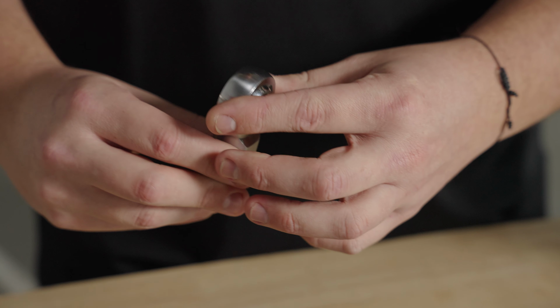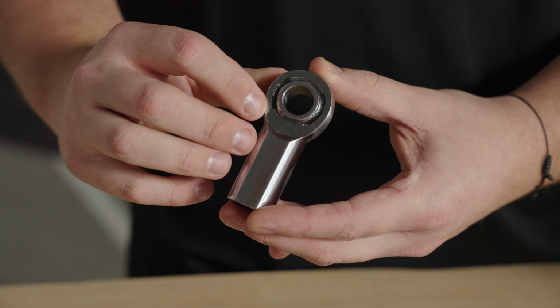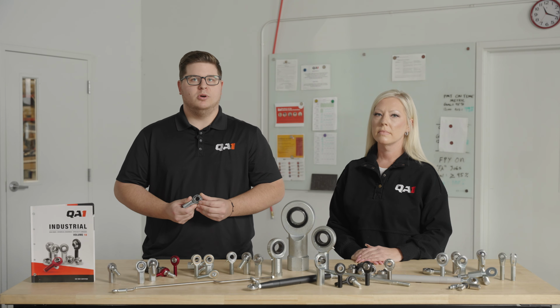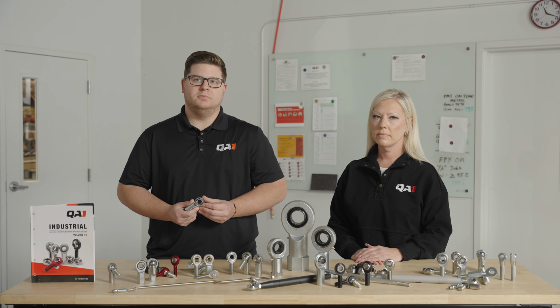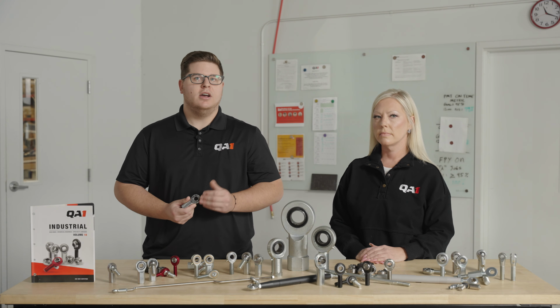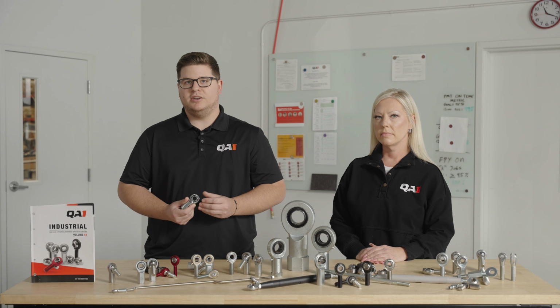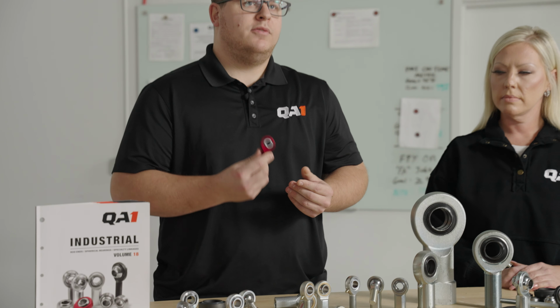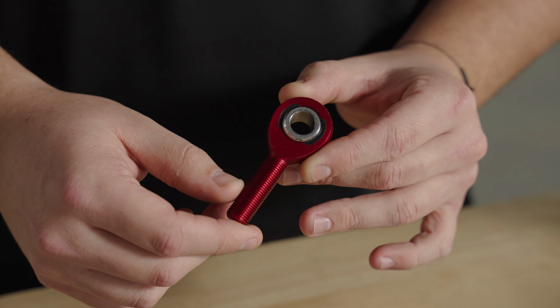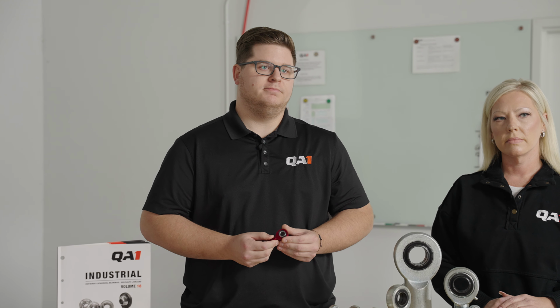The injection molded liner also provides lubrication and does a great job of sealing out debris and dirt. Loader slot rod ends are most commonly used in vehicle suspension and motorsports applications. QA1 X series rod ends are available in both inch and metric sizes. We also offer the A series loader slot rod end, which is made of aluminum, which can be used in applications where weight is a concern.